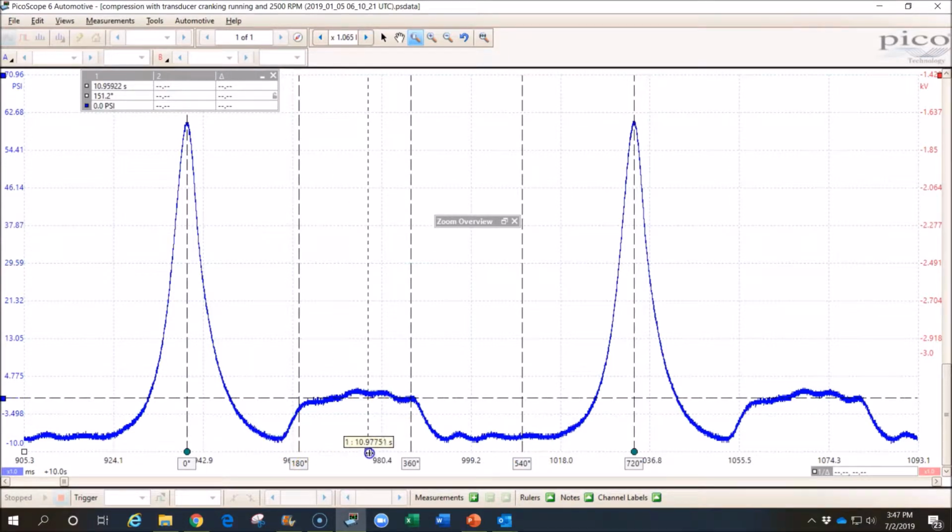And it's hard to tell, but we would typically say that it opened right where the pressure began to decrease. So right in this area somewhere, the intake valve opened. It is difficult to identify exactly where that happened. But we should see the pressure kind of trailing off towards the end of that. And then somewhere right in about here, the exhaust valve finally closed.